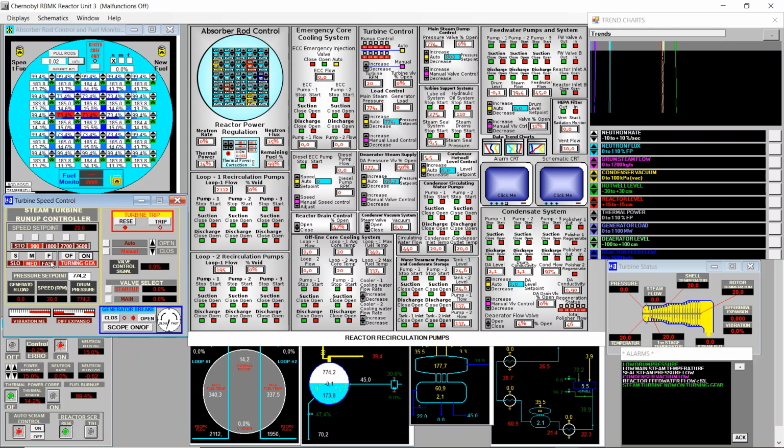This is quite slow, so now I want to try to do it manually and increase the rate of speeding up by opening the control valve more manually, and then we'll see how it works when we switch back to automatic at the end to keep the 3600 RPMs. We've got to watch the radiator pressure. Let's see what's happening.